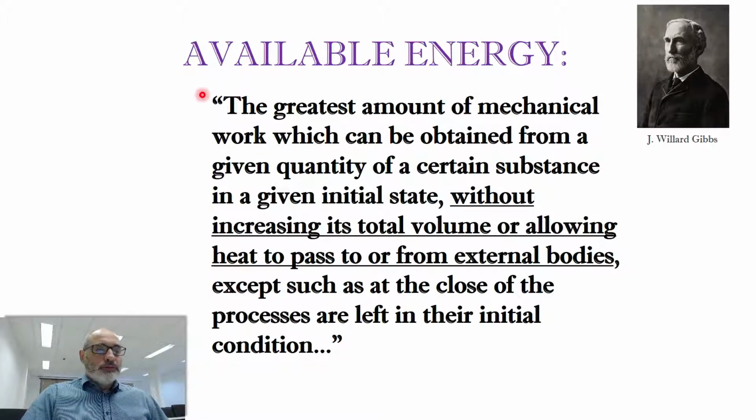So where was I? Yeah, the ideas of Gibbs. I was trying to recover his reasoning. Okay, so he thought of exergy as being the greatest amount of mechanical work, organized energy, which can be obtained from a given quantity of a certain substance in a given initial state, without increasing its total volume or allowing heat to pass to or from external bodies, except such as at the close of the process are left in the initial condition.